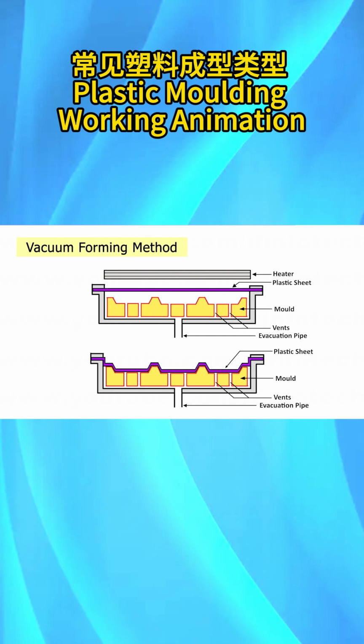Once the plastic sheet has cooled down to below its freezing point, the air flow is reversed to lift the forming off the mold and the mold is lowered. This process is used to manufacture a variety of products in thermoplastic material. The most popular material is high impact polystyrene. It is relatively cheap, comes in wide range of colors and it is easy to form.